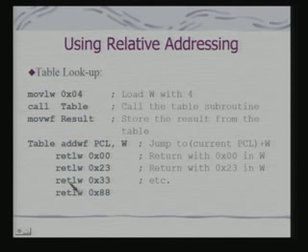What is the instruction in the table? The table is represented as a RETLW instruction. So, what does that mean? In this case, you return by loading a particular value onto W. So, a complete table lookup operation has been implemented, and implemented pretty efficiently with pretty high code density.